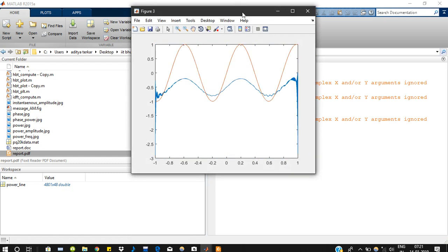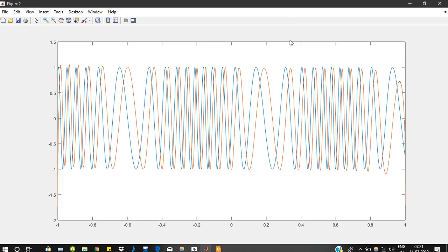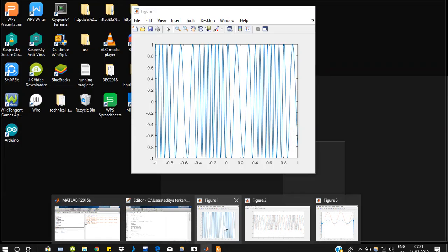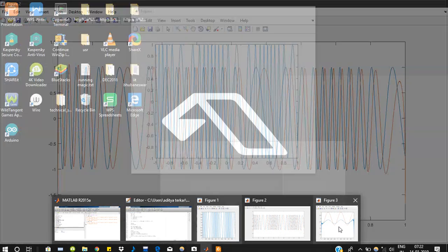Okay, so here we are with our results. You see the orange colored signal is the quadrature phase shifted signal. As you can see, where the sinusoid gets lower in frequency, it automatically also changes the phase shift, so that these two signal parts are again quadrature phase shifted. Similarly, as you reduce the frequency, it also reduces the delay, so that the quadrature phase shift is retained over the entire signal. By the way, this is our frequency modulated signal.